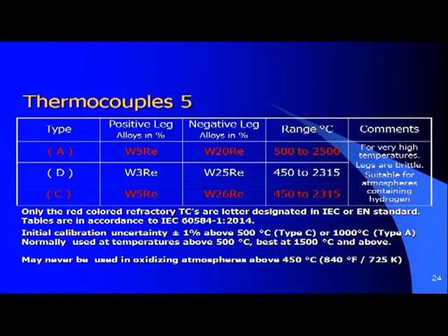The tungsten rhenium types are the only types under all thermocouples which are nearly immune against hydrogen or hydrocarbons. Anyway, if you have a process with higher temperatures and hydrocarbons or hydrogen in the atmosphere, you have no other choice than using a refractory element. In a hydrogen-containing atmosphere, the lifetime of noble metal thermocouples is counted in weeks, even hours.